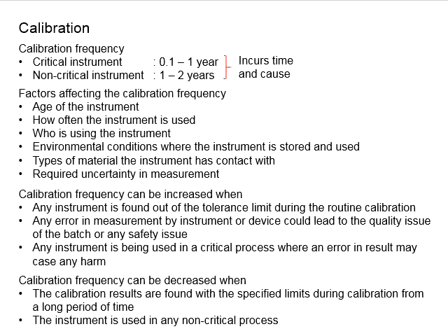In terms of the calibration frequency, normally they classify it into critical instruments or non-critical instruments, as defined by the labs. For the critical instruments, normally the frequency will be higher, and for non-critical instruments, the frequency will be lower. This is of course subject to the budget that the respective lab has allocated for calibration purposes.